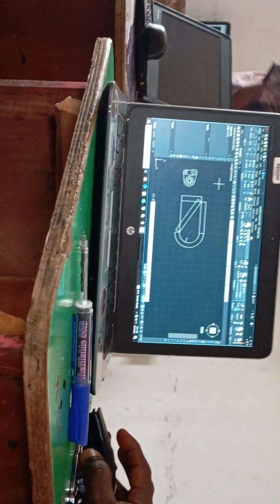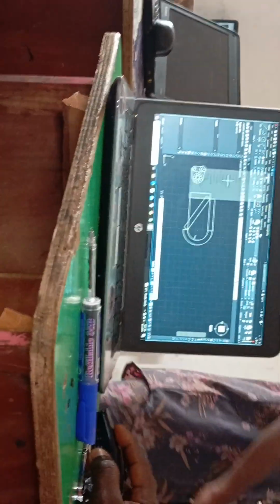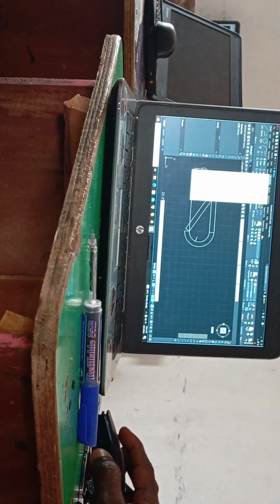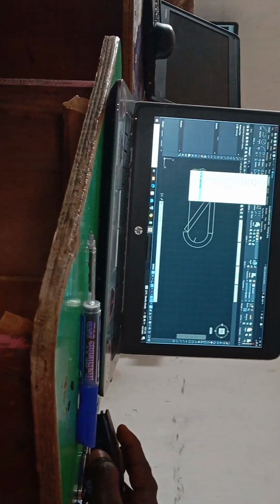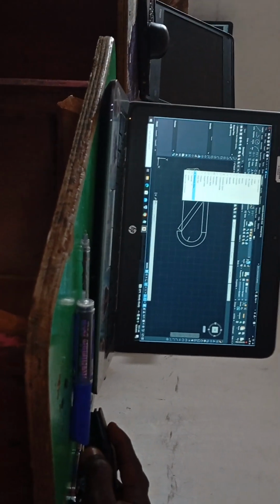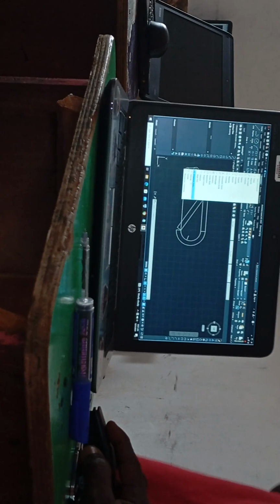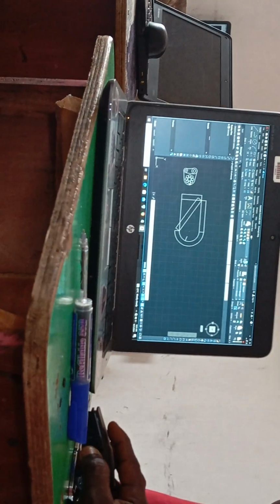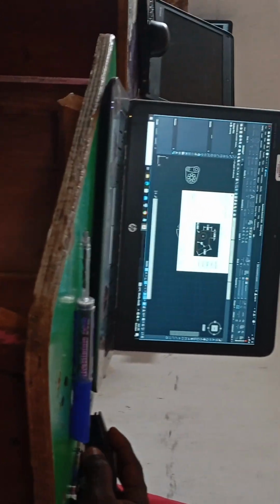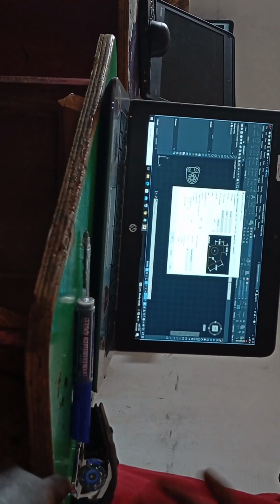So, let me use the word, you engineer your text and related parameters. You go into dimension, from dimension to quick. Go to dimension on menu bar, click dimension style, click modify. From menu bar, click dimension to dimension style to modify.